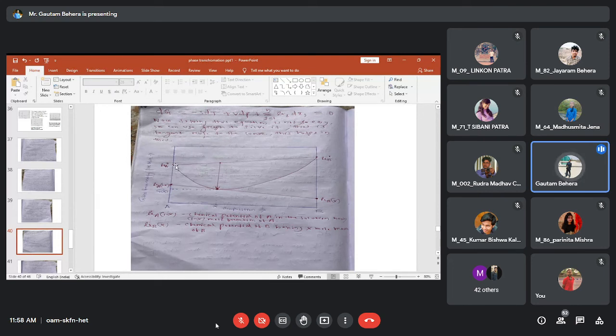And this straight line, you remember, is the mechanical mixture free energy, and this inverted parabola is the solid solution free energy, right? And you know the tangent. This is the tangent drawn at a composition of x, right? At this particular composition x, this tangent will intersect the pure component A and pure component B axes. That will give you the chemical potential.